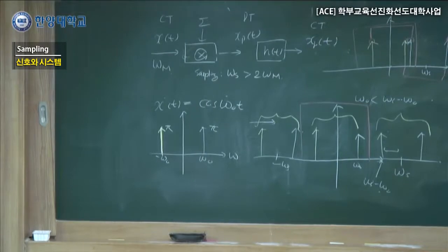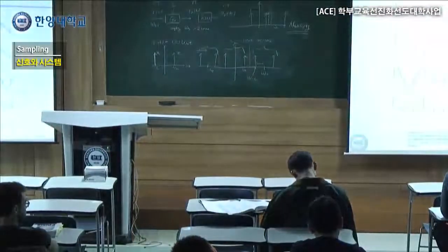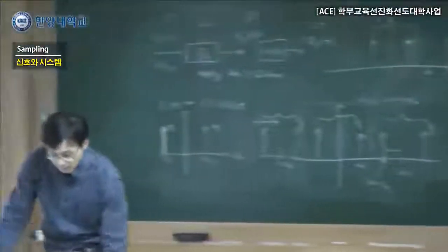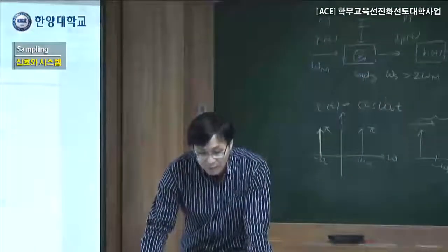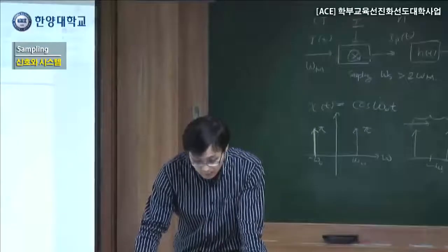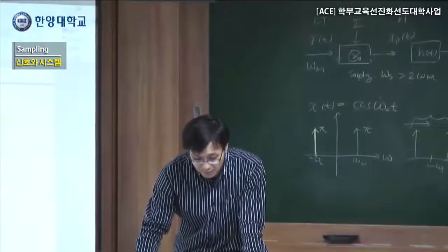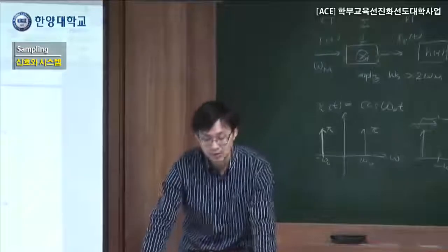When aliasing happens, it's very difficult to find our original data, because the number of our samples is not enough, meaning our sampling frequency is too small. So a way to do that is to increase your sampling frequency. And if you increase it even more, it may be okay, but in this example it's impossible to reconstruct how it actually looks.